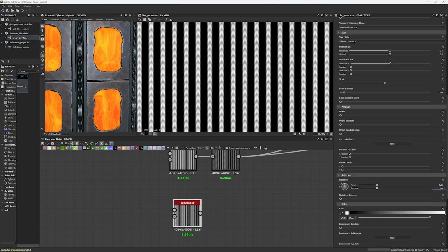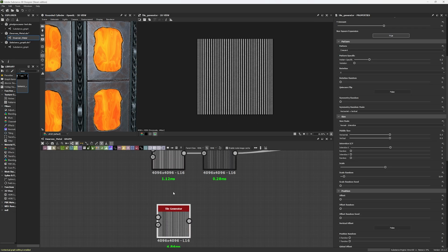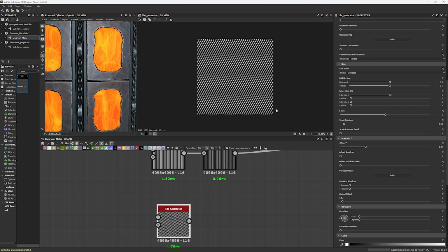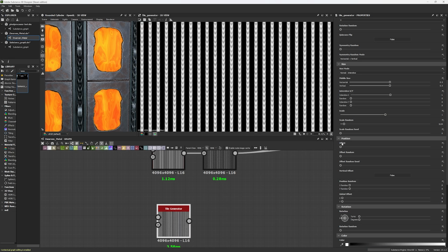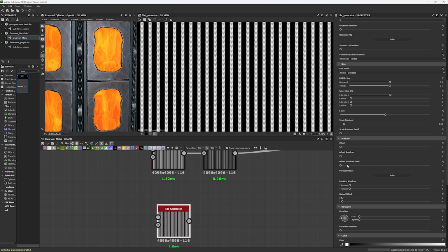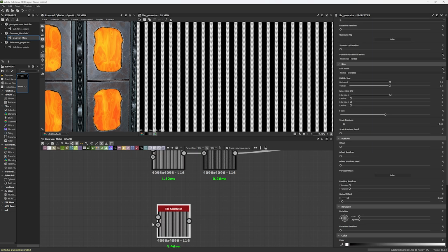As you can see, you can change this to be in the other direction by setting this to -90. Now you have exactly the same one, but with a little bit more of an offset. You can do this again with this kind of offset, but sorry, it's not going to work with this one, because it's going to be offsetting each individual shape. But if you do a global offset, that should work. We need to use a global offset of 0.063 in order to make them match, because that's the space we have between those lines.